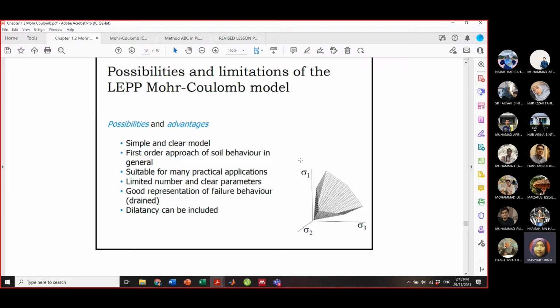So you need to find out what is the best constitutive soil model that can explain and tell you the retaining wall behavior when it is subjected to excavation stages or excavation process. This is very important for you to have some overview about the software, about the site project, about the input of the materials.